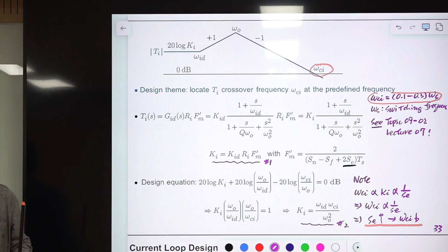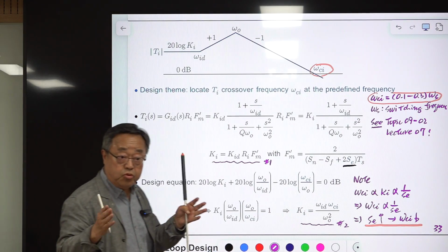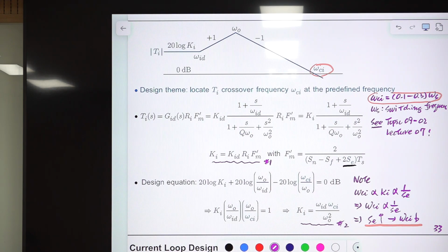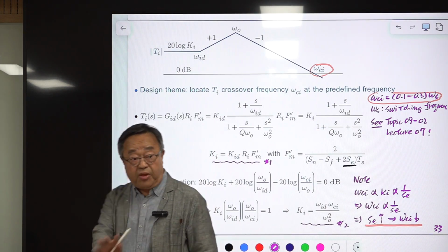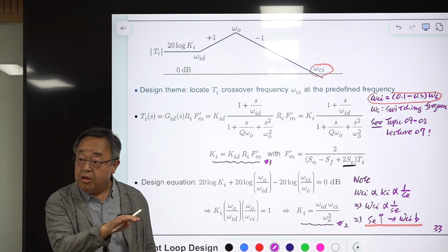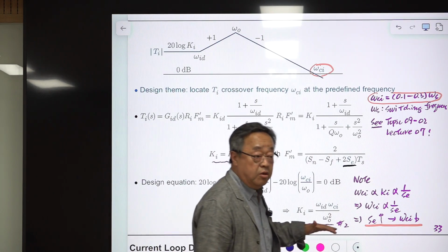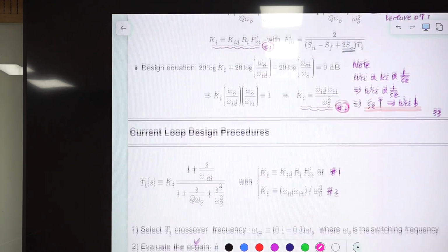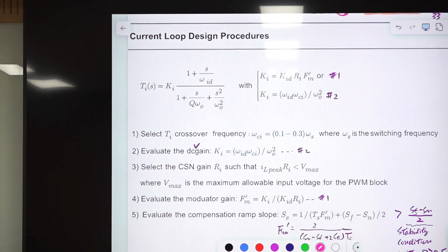Okay, again, for that case, you have the structure of current mode control. You have the current sensing network, external ramp, but functionally, in dynamics, that becomes voltage mode control. That design cannot be applied to boost and buck-boost converters. If that design is applied to the buck converter, closed loop performance will be very poor. Okay? Right. So I marked here, this is equation number 1, and this is equation number 2, and the design procedure for the current loop is extremely simple.